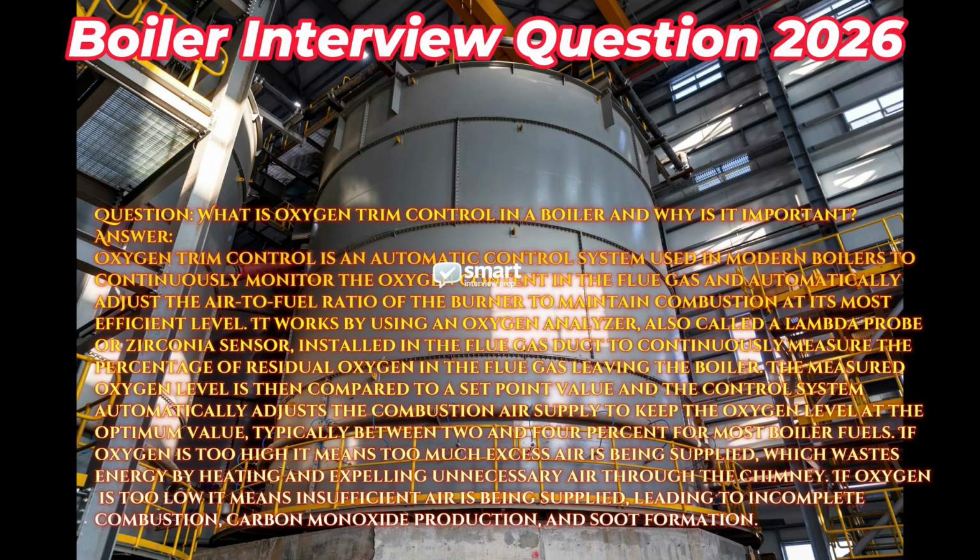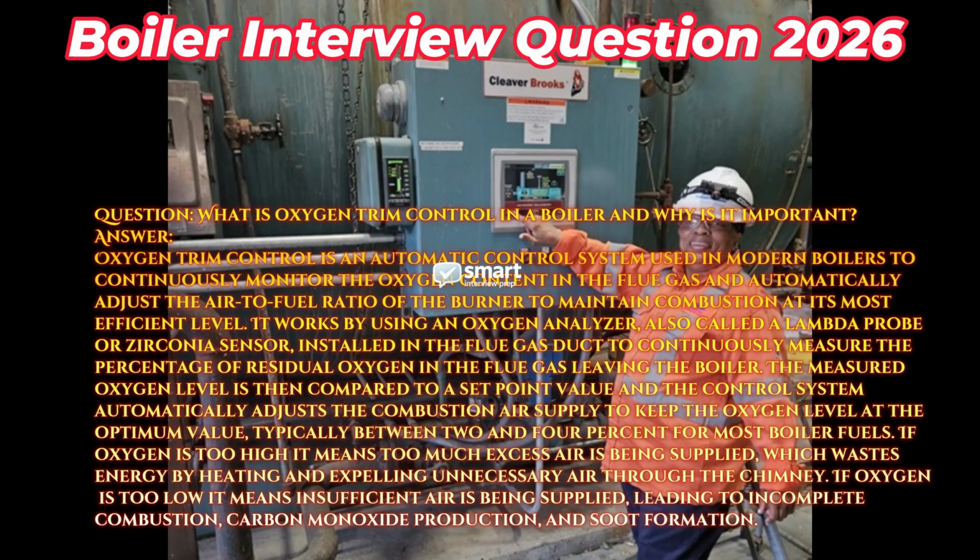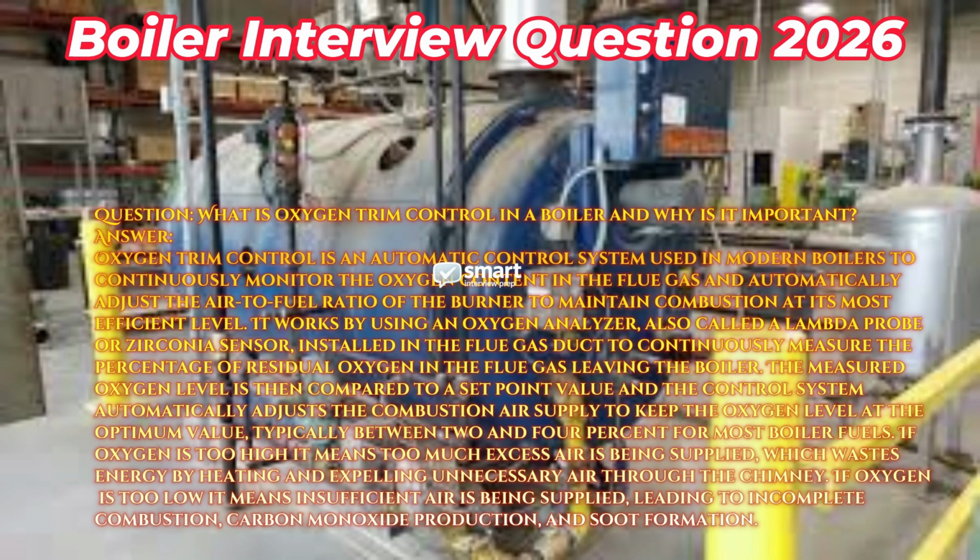Question: what is oxygen trim control in a boiler and why is it important? Answer: Oxygen trim control is an automatic control system used in modern boilers to continuously monitor the oxygen content in the flue gas and automatically adjust the air-to-fuel ratio of the burner to maintain combustion at its most efficient level.